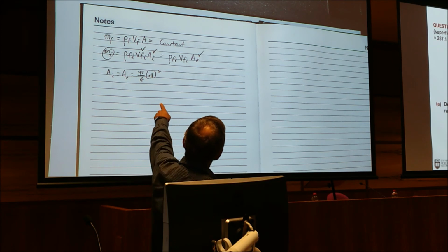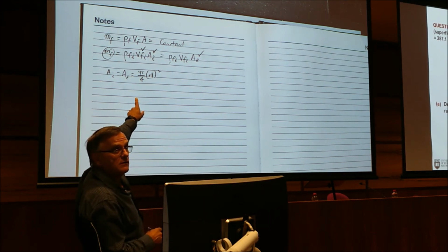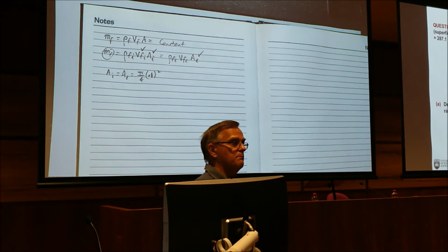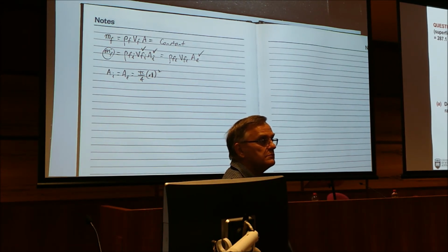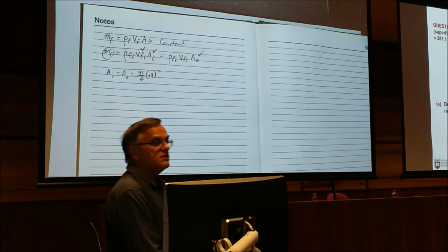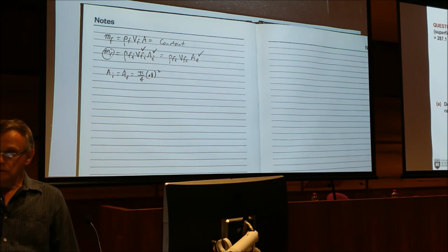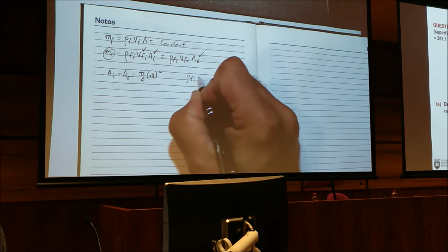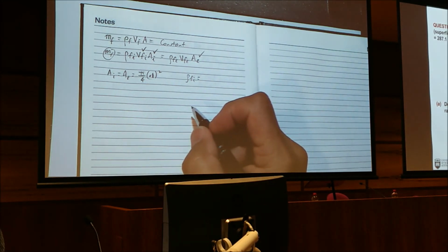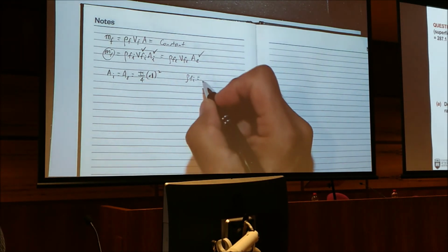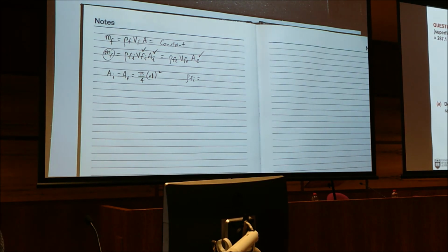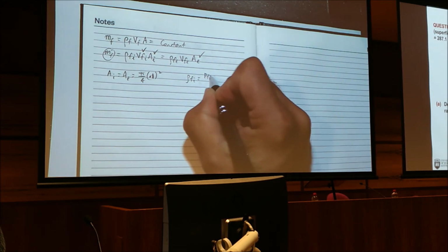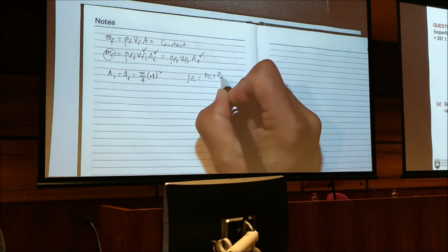Now we've got a better chance using the first equation, don't we? Now the question is, can we determine rho Fi based on the given information? Yes. So rho Fi, we'll use the ideal gas law, is the absolute pressure at the inlet, which is the gauge pressure at the inlet plus atmospheric pressure.